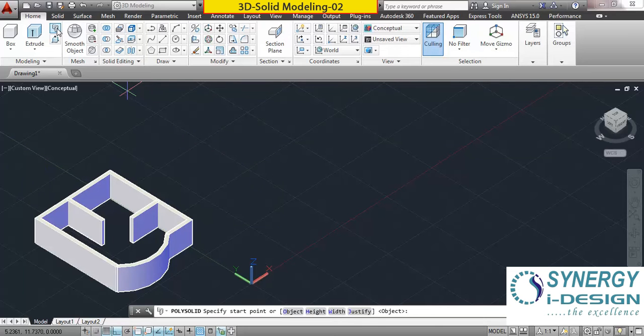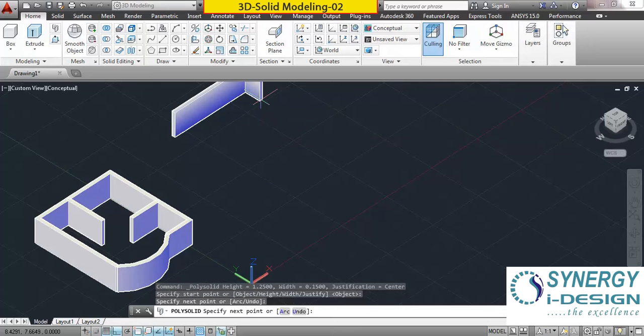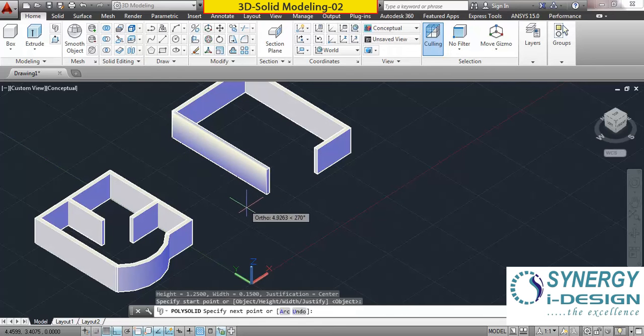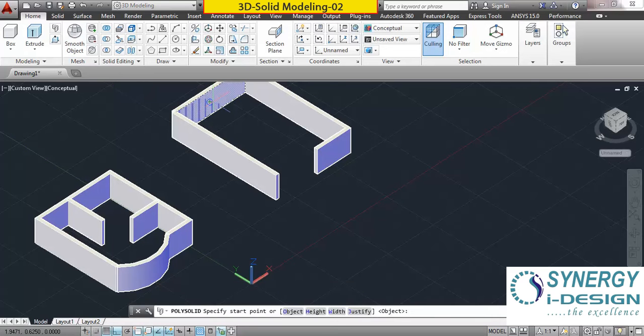What we can do is take the help of Polysolid like this, and then I can draw a line like this, like this, like this. Now if we see the command here, I am taking the sub options: R, close and undo. Currently I am in a line command, like a wall command. I come into the R, and for R I type A. Again I take the command A, press enter to confirm.